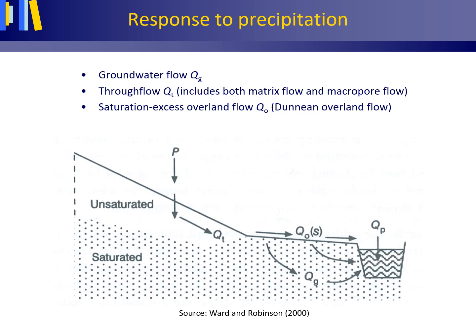Macropores are pores with a diameter larger than 30 micron and relate to porosity around soil aggregates. A special type of both through flow and macropore flow is pipe flow. Pipe flow is rapid through flow bypassing the soil matrix, for instance, when water flows through burrows made by moles or voles, or when it flows through artificial drains.